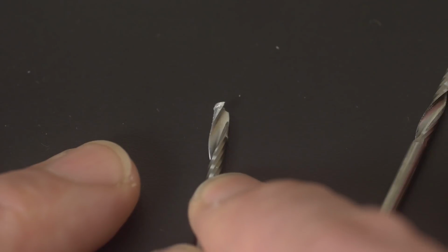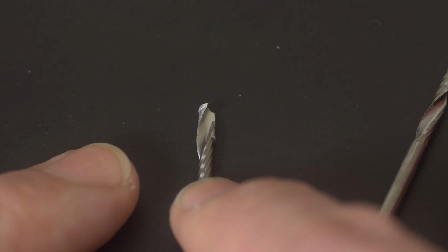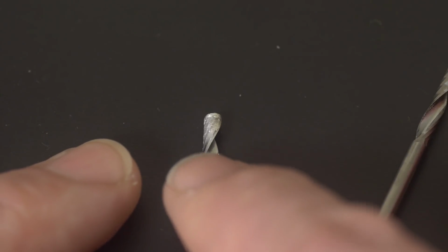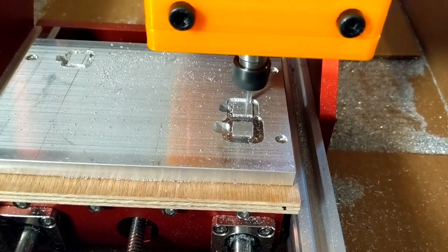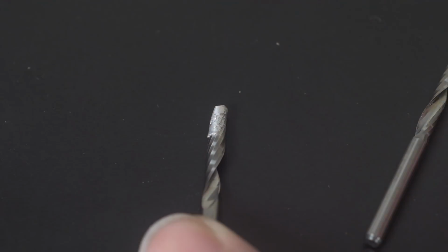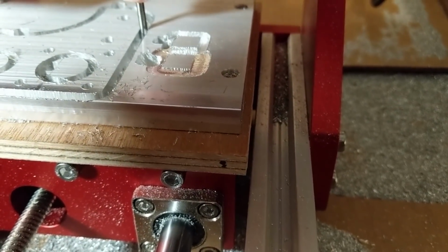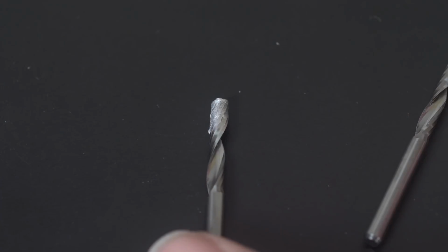And the problem is that while I haven't broken a bit and the geometry seems to be cutting acceptably, the chatter, oh my God, it was so bad. And it's warbled out that hole, or that slot, quite badly to where there's a lot of play. Like this bit should fit in there with no play. It should not wiggle side to side, and there's a lot of wiggling there.